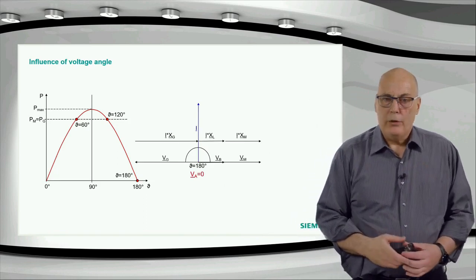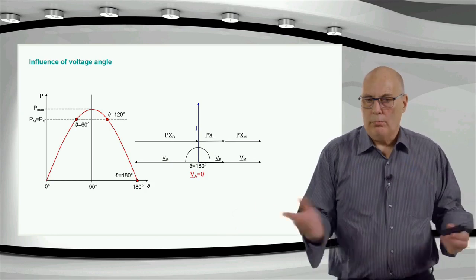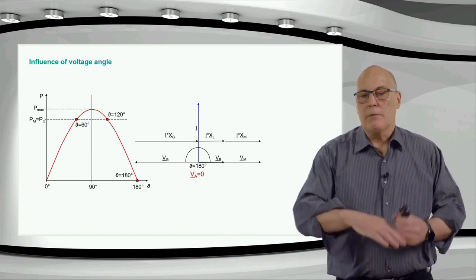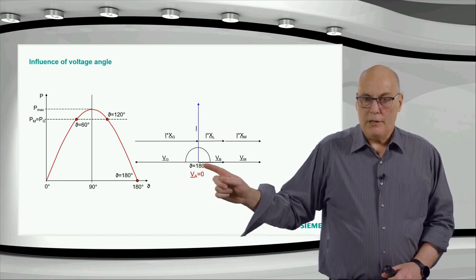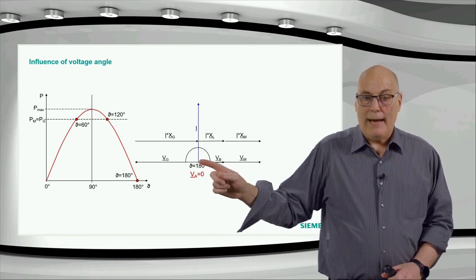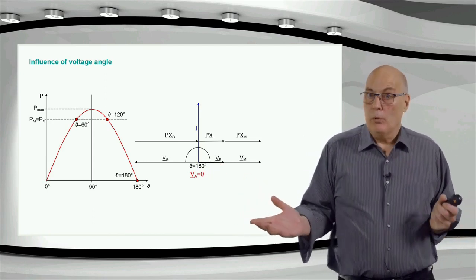Another interesting point is 180 degrees down here. It's the so-called out of step point. That's where the systems have turned completely open. It's very interesting in terms of our distance protection. You can see here what happens at our relay A: the voltage is now 0. What will the impedance be? The impedance will also be 0.